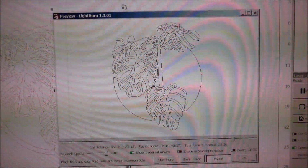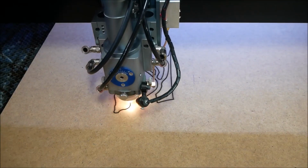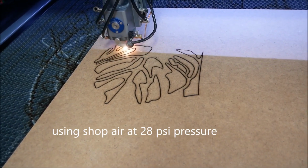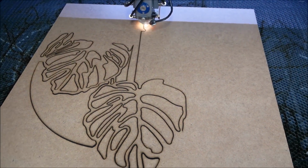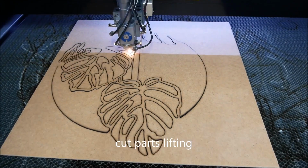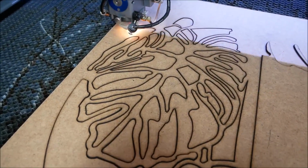The next step is to load the panel onto the laser bed, so I'm using a hardboard panel. Laser set up at about 32% power at about 0.477 speed. I'm also using shop air pressure at about 28 psi. The cut's coming along quite smooth. What I check here is that the odd piece lifts up a bit. That tells me that the laser settings are correct. This 1/8 inch hardboard is fantastic for cutting. It's very smooth, very detailed cut.